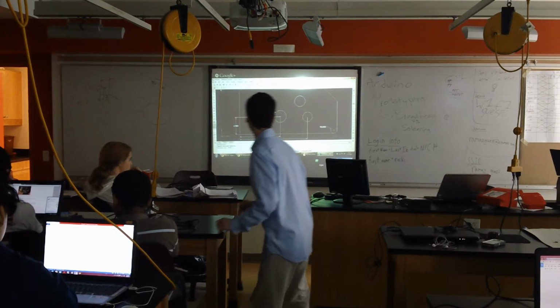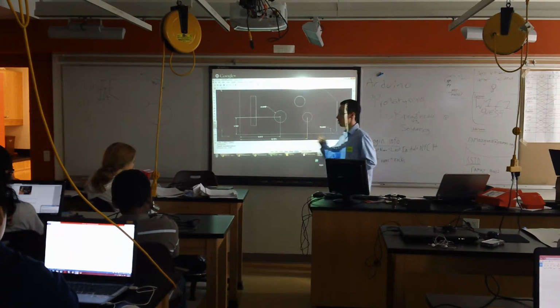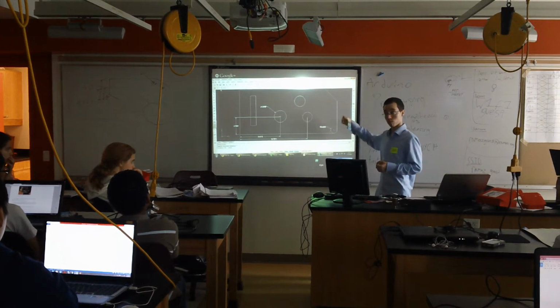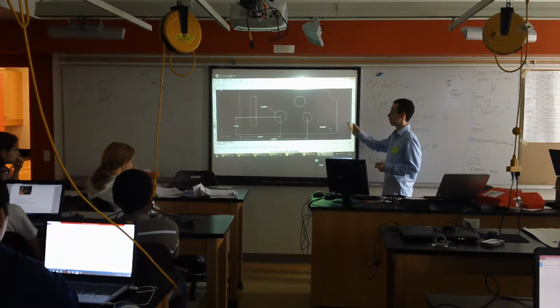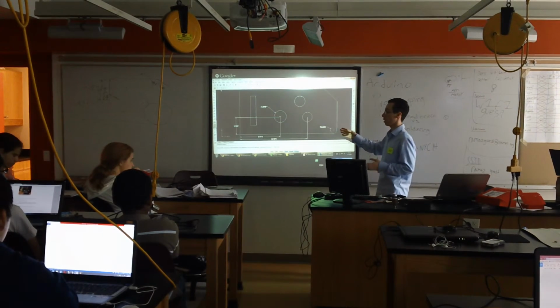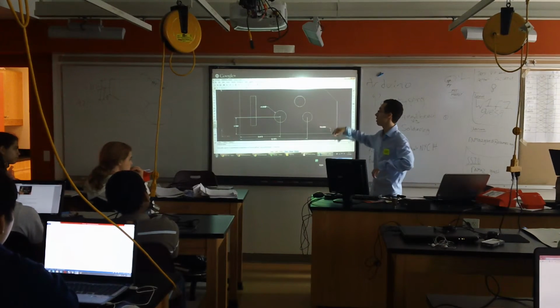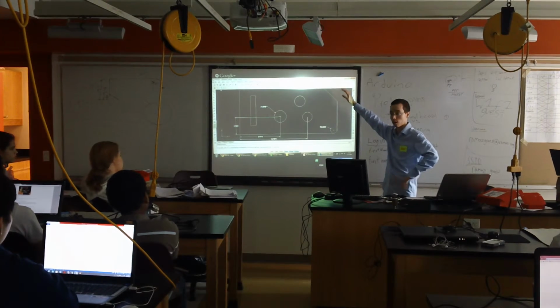In 3 dimensions, yeah. So this is a 2-dimensional part, right? We have no idea how thick it is. If I want to dimension a 2-dimensional part like this and I know how thick it is, one way to do it, if it's just a plate with a bunch of holes in it, is to put a mark up here that says, hey, this is 1/2 inch thick, and that's okay.